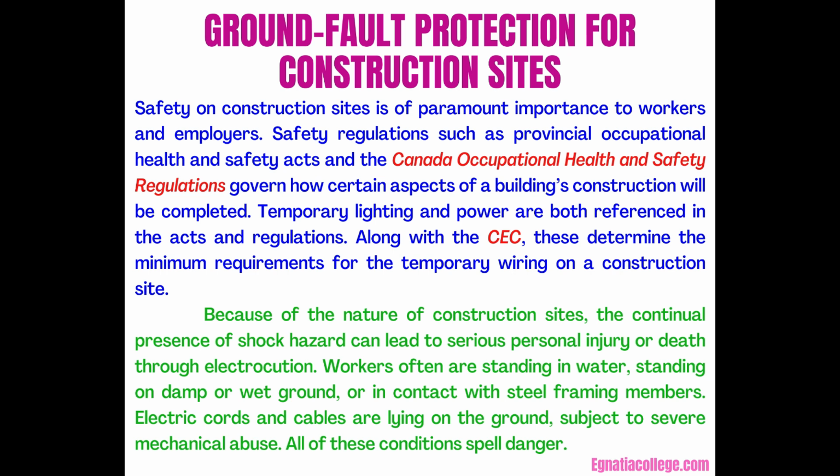Because of the nature of construction sites, the continual presence of shock hazard can lead to serious personal injury or death through electrocution. Workers often are standing in water, standing on damp or wet ground, or in contact with steel framing members. Electric cords and cables are lying on the ground, subject to severe mechanical abuse. All of these conditions spell danger.